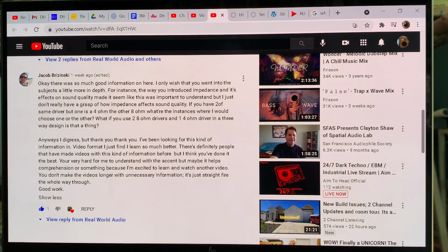I would say when you are starting out, it's safer from the design process to use the 8 ohm driver, provided your amp has 8 ohm taps. Because even though, let's say you have a solid state amp and it has both 8 ohm and 4 ohm taps, but you design a 4 ohm driver, 4 ohm speaker, you don't know how well your amp can handle dips down to below 4 ohms.